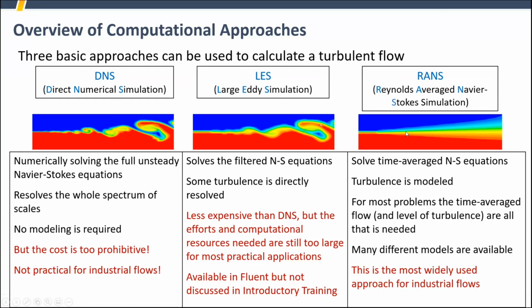So you have things like our turbulent kinetic energy, rather than actually directly modeling the kinetic energy. When you're modeling the velocity of this eddy directly, the velocity is the kinetic energy. When you're not modeling that swirling flow, you have to have a representation of what the turbulent kinetic energy is, and that's our K value, in the K omega or K epsilon. And things like eddy viscosity ratio you'll have in here. So our eddies are actually directly picked up in here, but in here we have our eddy viscosity ratio. Okay, so those are the kinds of parameters that they're using to represent what's actually happening.